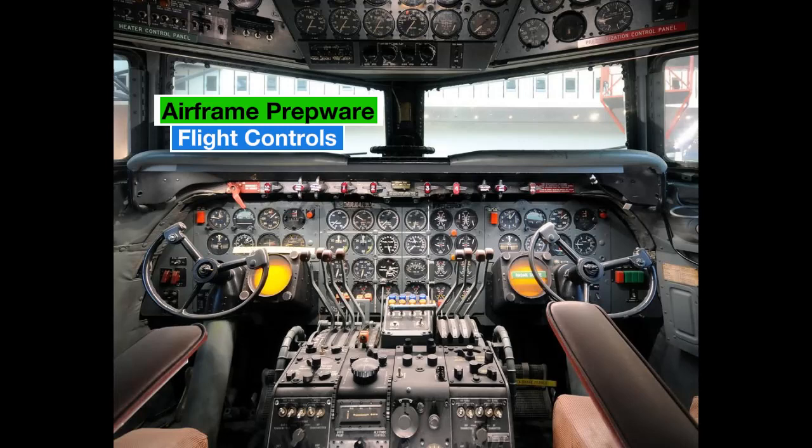What type of flap system increases the wing area and changes the wing camber? Fowler flaps. Dutch roll, a combination yawing and rolling oscillation that affects many swept-wing aircraft, is counteracted with a yaw damper system.